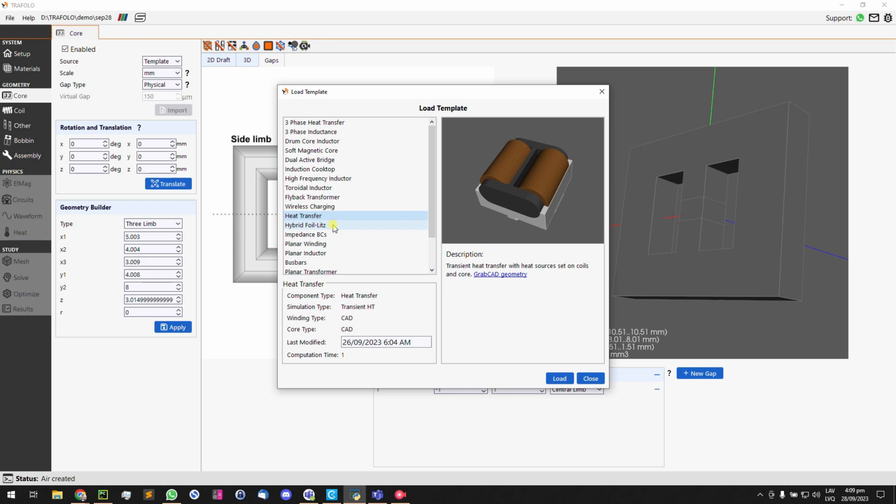I see that there are other questions. How about different materials such as ferrite, nanocrystalline, amorphous, etc.? Also for the gap, is there a possibility to use materials of different permeability in the gap? Let's start with the last question, whether there is possibility to use materials of different permeability in the gap. The answer is, I think, yes. I have never tried.